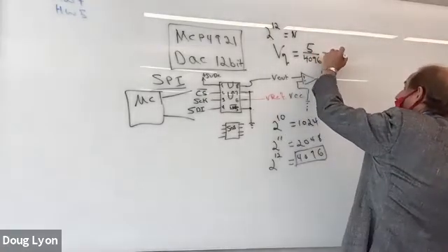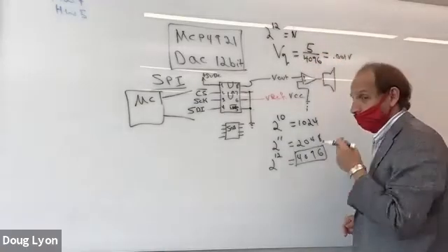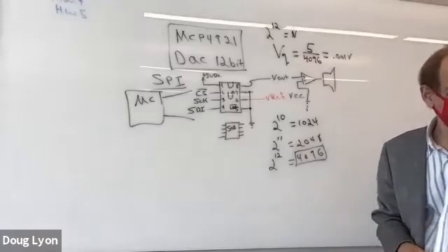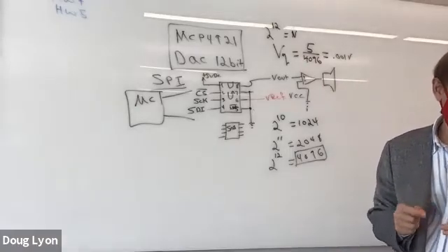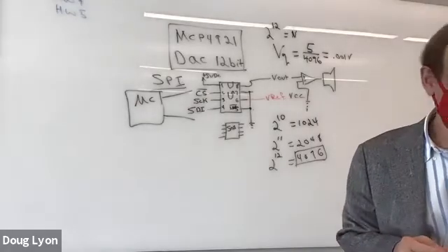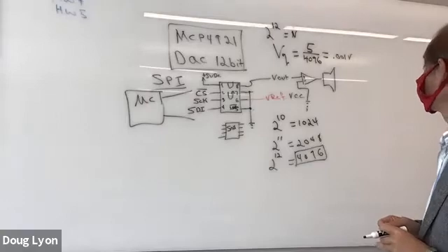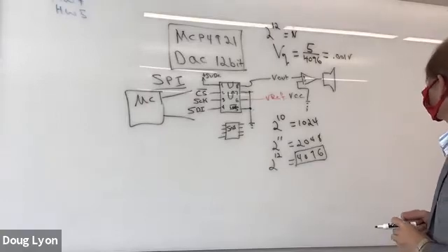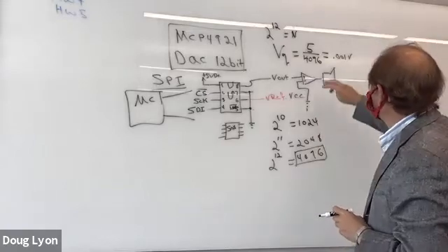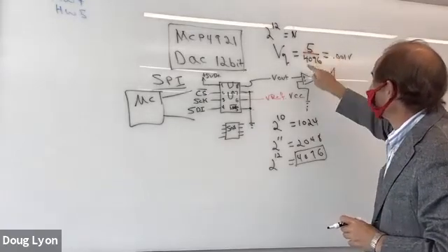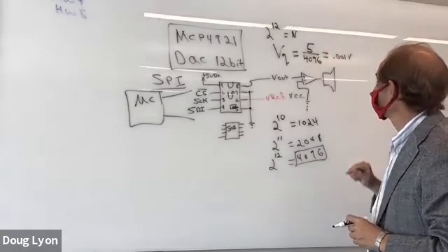So that 0.001 volts is your voltage of quantization. That quantization noise is the minimum voltage you can detect, or actually produce. And if you think about it, you might do better if you made the full deflection go from 0 to 1 volt instead of 5 volts.